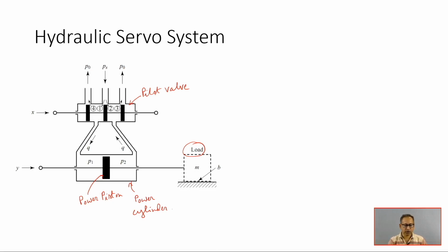Okay. So, this pilot valve is a balanced valve in the sense that the pressure forces acting on it are all balanced. A very large power output can be controlled by a pilot valve, which can be positioned with a little power. That is why it is called pilot. So, you have to apply little power, but it will control a large amount of load. So, that is why it is called pilot operation. Okay. So, this particular system is also termed a servo system.